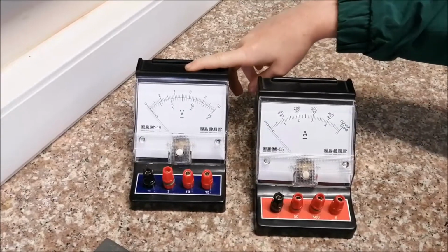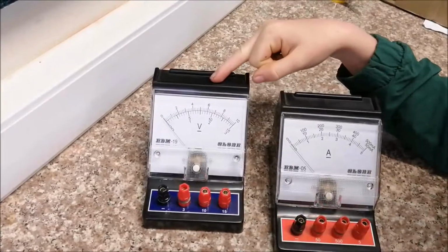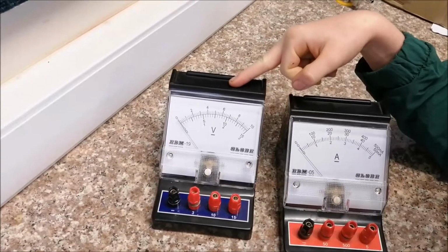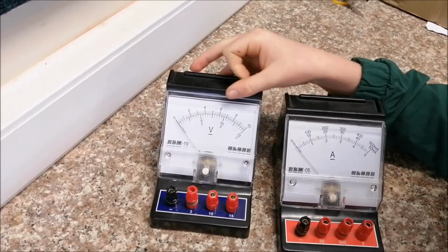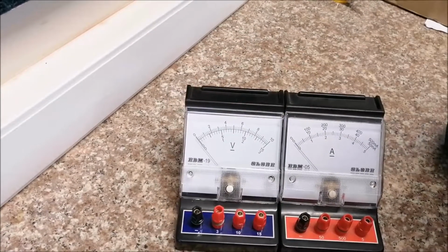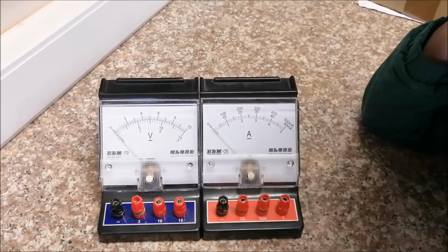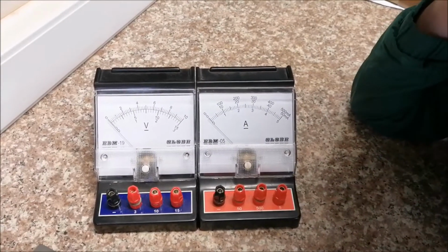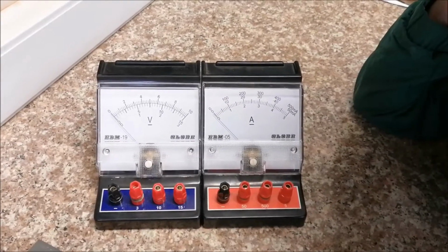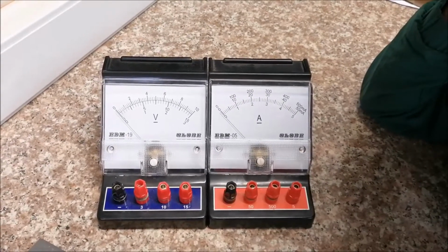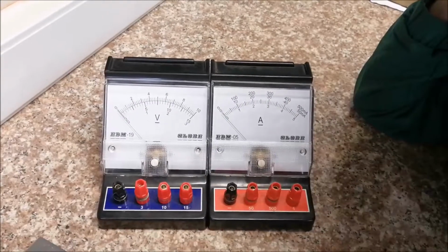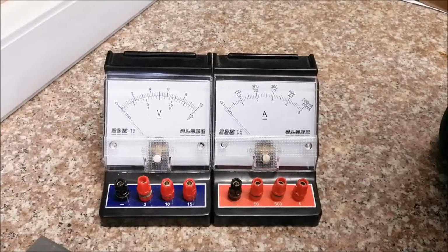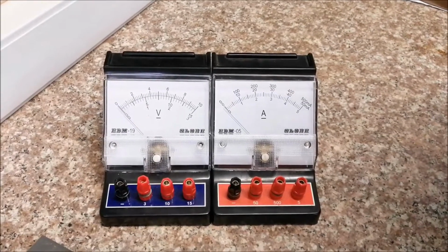So we have an ammeter and a voltmeter. A voltmeter must be connected in parallel. So you'll see the way that we connect it up so that it gives us an accurate reading, that we connect that meter in parallel, whereas the ammeter must be connected in series, or in series with part of the circuit. So you must understand how to connect those various apparatus, and we will look at how we represent these in a diagram today so that you know what you are drawing.